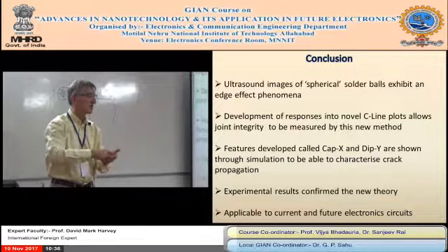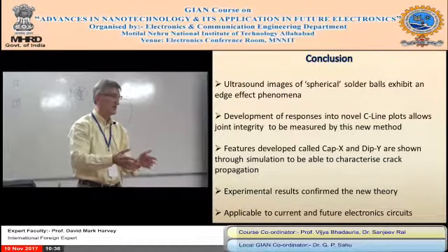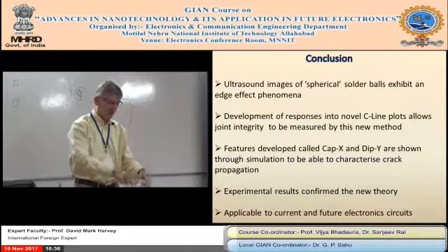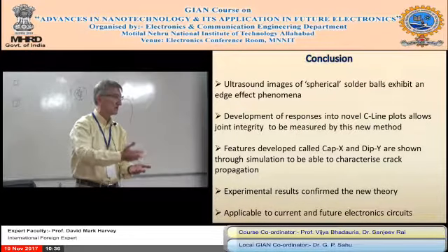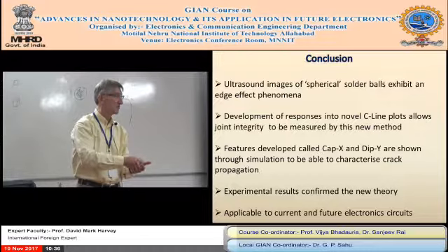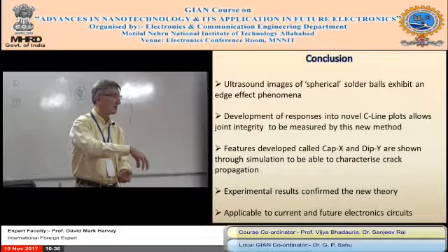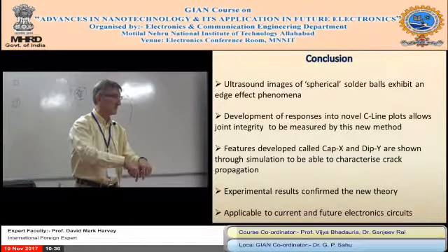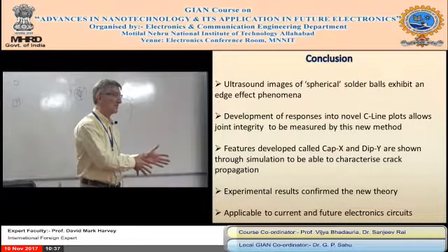Actually, we can look inside the chip. One thing we do is called die etching. Have you heard of this? You want to look inside the chip, and it's a plastic package. You put the package down and use some acid, and you can burn off the top of the package rather than using mechanical force, which is what you're talking about. So you burn off the top, and maybe you can look in first with an optical microscope, and maybe even probe electrically inside.